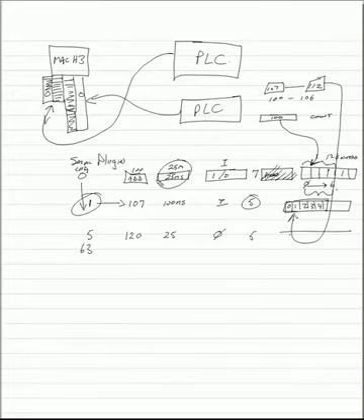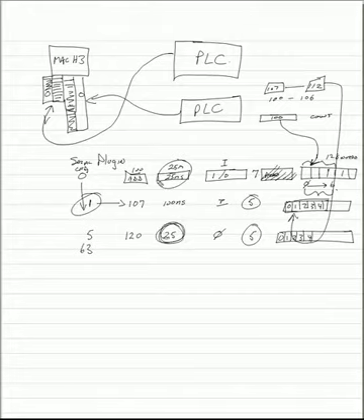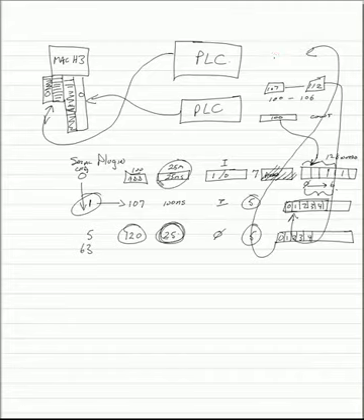This would mean that in the data buffer for configuration 5, we're going to take 5 registers, 0, 1, 2, 3, and 4, and every 25 milliseconds, we're going to transfer them to the PLC at address 120. Therefore, these 5 registers, every 25 milliseconds, will scoot up here and be put into memory address 120, 121, 122.